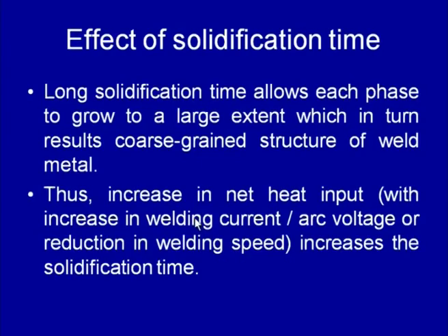So, in general if we increase the heat input, then the solidification rate is decreased, a decrease in solidification rate increases solidification time, and increased solidification time results in a coarser grain structure. A similar effect is observed with the increase of the initial plate temperature, because increased initial plate temperature, or the preheating, also helps in reducing the cooling rate, and a reduction in cooling rate increases the solidification time, and increased solidification time coarsens the grain structure.